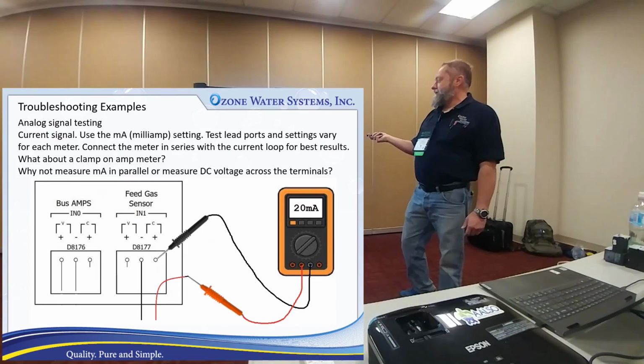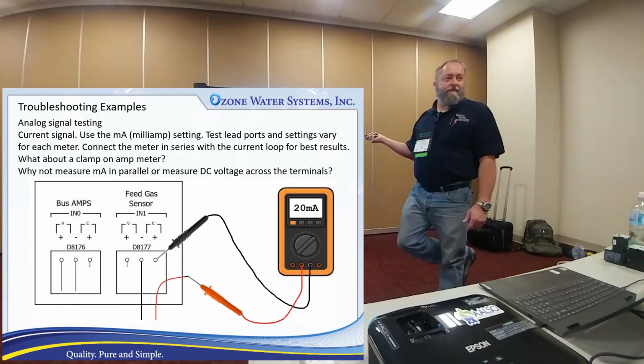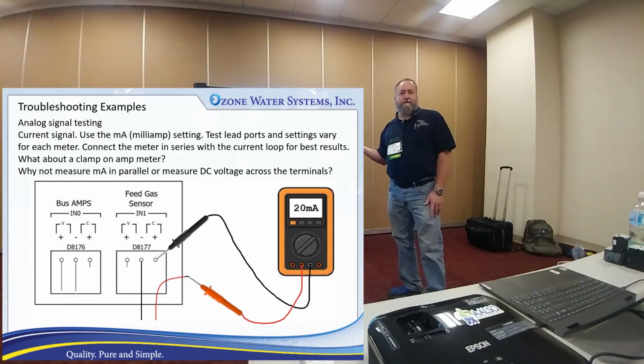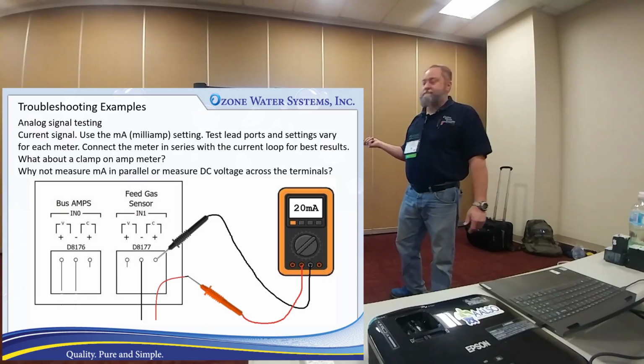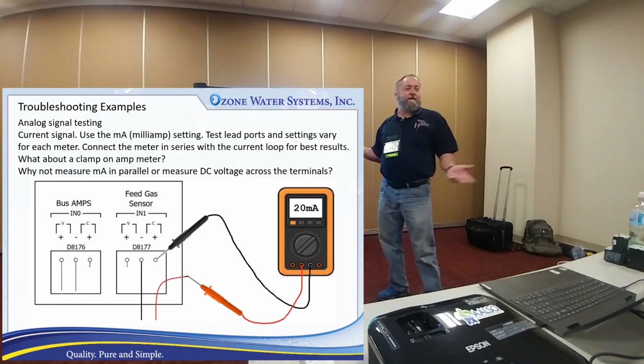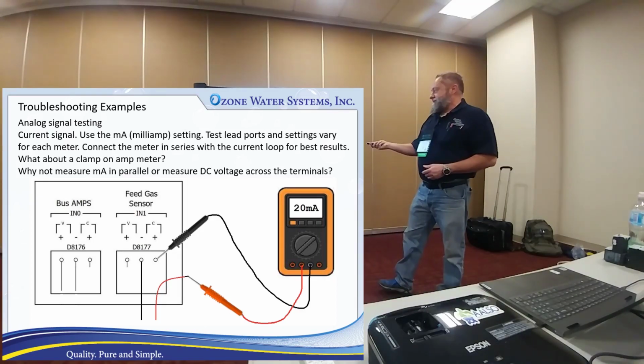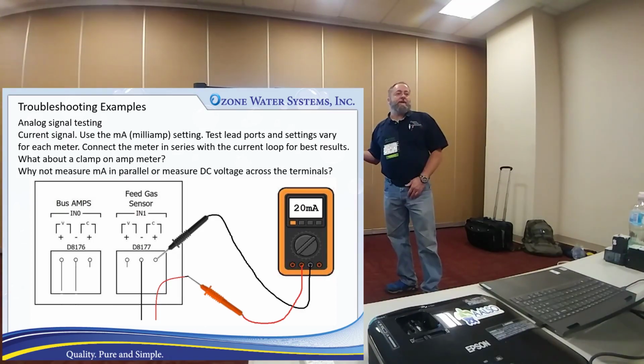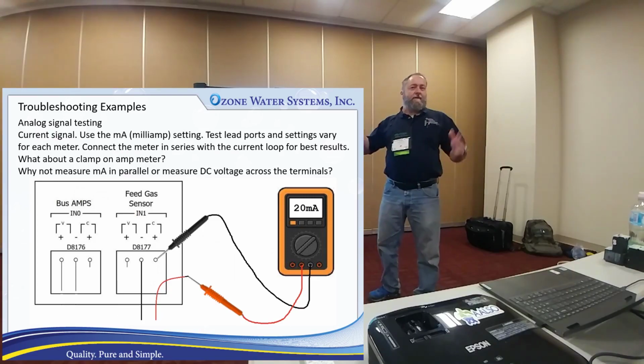But they're not all 250 ohms. Like that PID controller, that's a 2.4 ohm load, or a resistor across that. It's going to be a completely different number. Some of these are 500 ohms or 70 ohms, some Allen Bradley stuff. So they're all over the board.